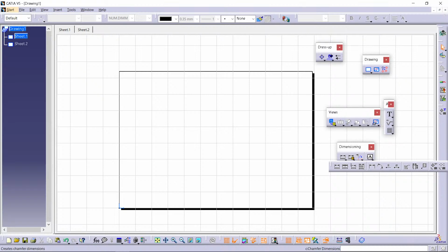This is chamfer dimension, if you have given any chamfer, then thread dimension, which will give you the thread value, and here coordinate dimension, the whole dimension table, and coordinate dimension table. So in dimension you will get the dimension types, and here this is rerouting. This is for reroute or relink; these tools are used to relink the element or relink the dimension.